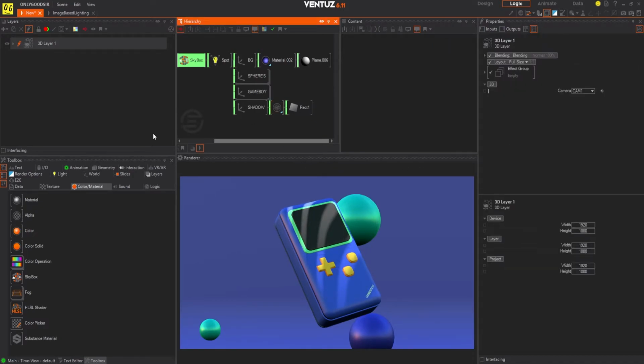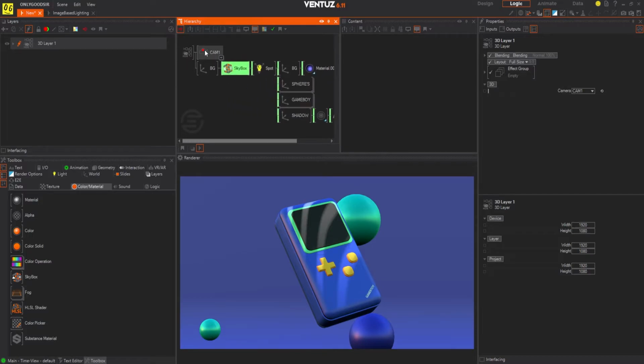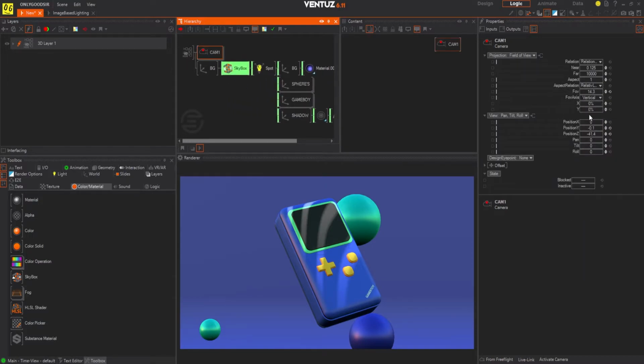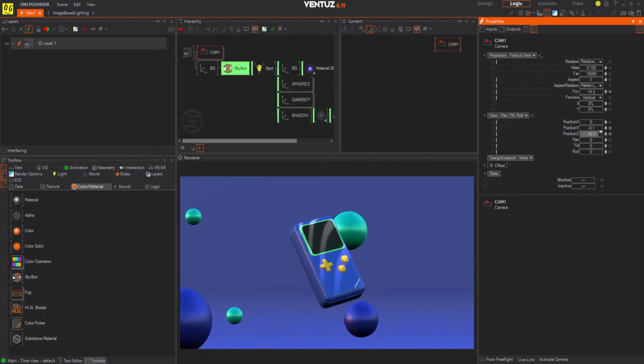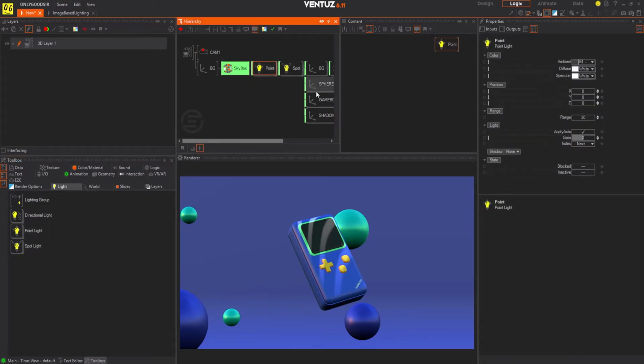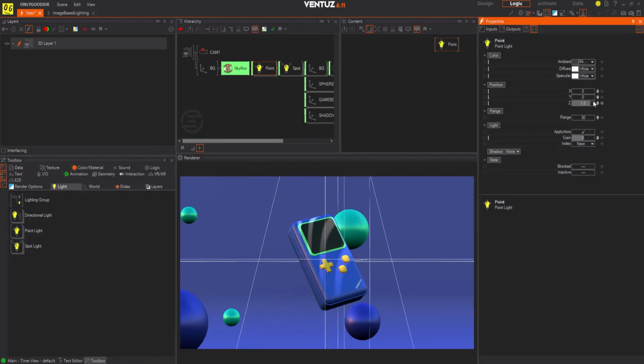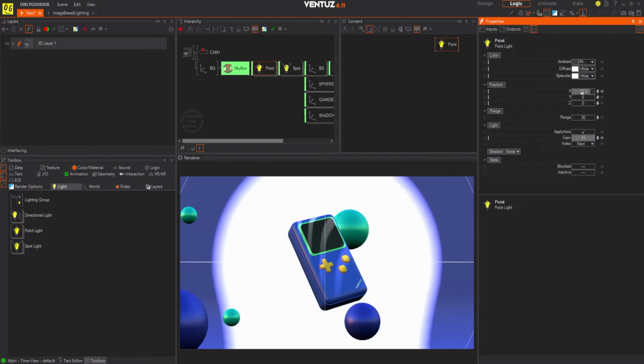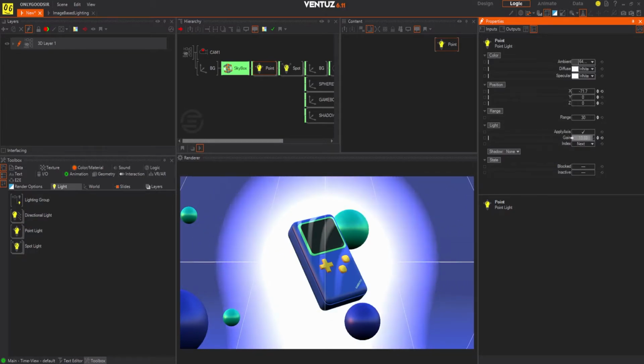Okay, so I'm going to add a backlight in here. Sorry, I could be here all day tweaking the colors and materials and everything. But I'm just going to add a little point light into the scene. So I'll drop a point light in, turn my non-render objects on so I can see that. And as you can see, I can position this at the back, increase that gain. So now you can see I've got a backlight. It's really, really powerful, so I just put that to 60.